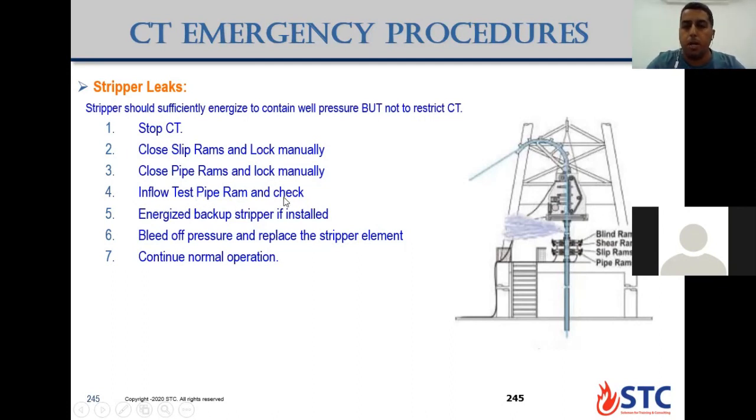Inflow test the pipe ram and check integrity, it's holding pressure from below. You will release any pressure above. Energize the backup stripper if installed. If you have dual strippers, you now have two barriers to fix the upper stripper. If not, you will bleed off pressure.